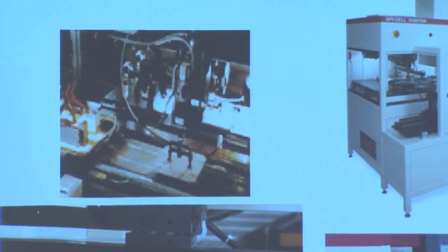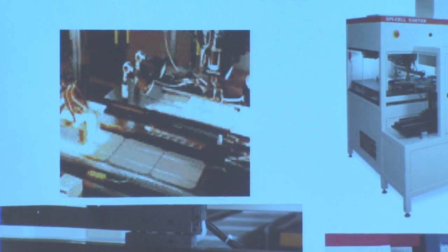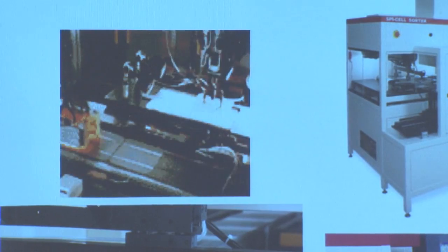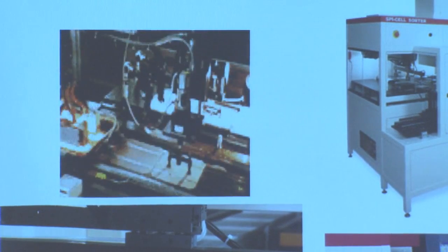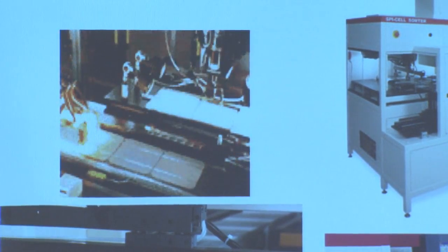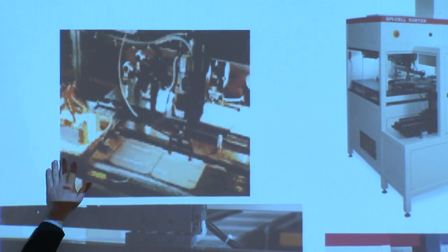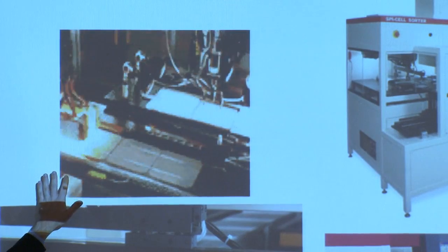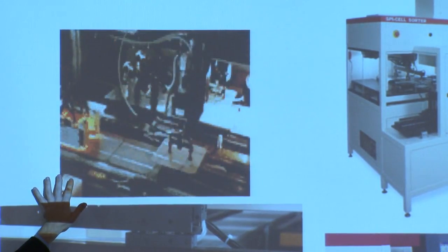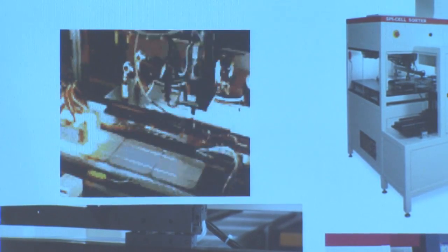Cell efficiency measurements are always tricky because depending on where you put your probes, your measurements are going to change because of the series resistance. So these probes right here are long and they contain multiple contact points, and they're essentially touching the bus bars, and light flashes onto the device, simulating the sun, so simulating AM 1.5 conditions, and an IV curve is measured.